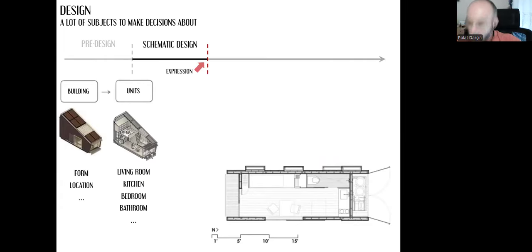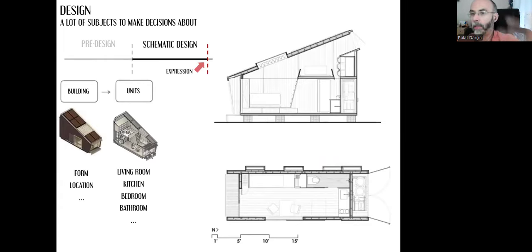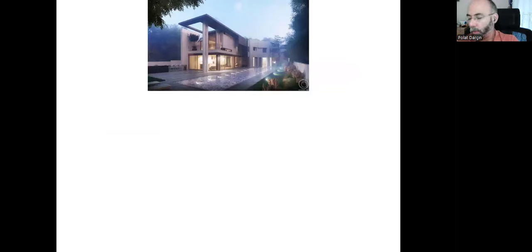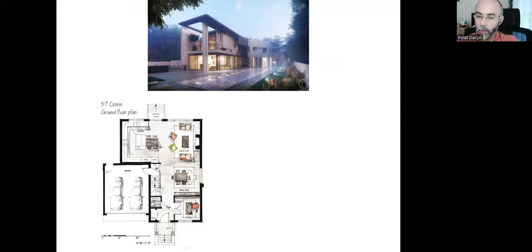Plan is the horizontal section of the building, and this is the vertical section, obviously. And anyone who looks at those drawings can easily understand the living areas, the living spaces, and the final visual aspects of the building. The users don't need to be educated in terms of technical drawing. However, these drawings we generally create at 1/100 scale, and of course we can do renders, we can do models.